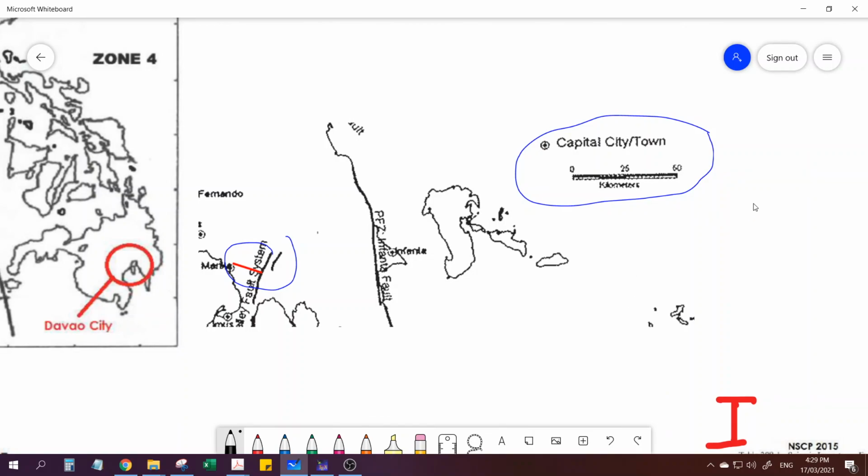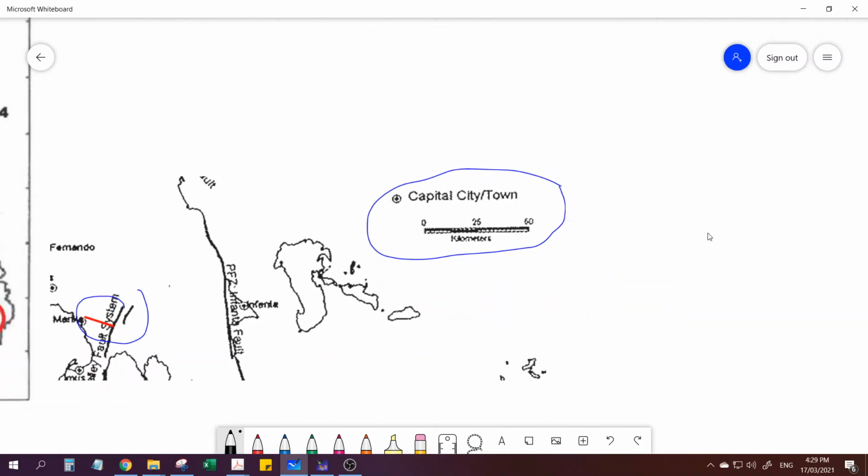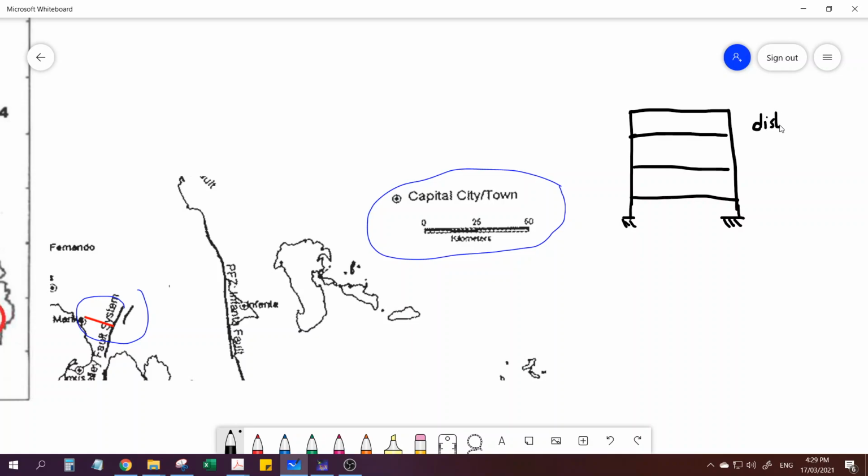So for example, your plate, say it's a 4-story. Okay, so say this is your project located in Manila. So your distance to the nearest fault line is equal to 10 kilometers. And on our example project, the importance factor is 1.5 because this is a school, as you will see later.